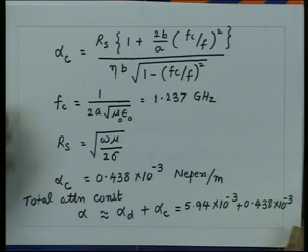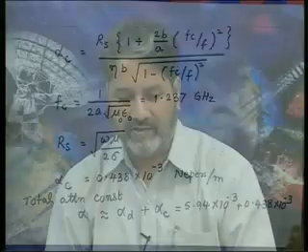So, these are some of the representative examples which you will see for the waveguide. Typically the waveguide dimensions are given, the frequency of operation is given, and we have to find out the modal characteristics of the waveguide, that is, how many modes will propagate. And also we have problems where a dominant mode is propagating on the waveguide, and then we would be interested in finding out how much power will flow, what will be the field expressions for that mode, what will be the Poynting vector, what will be the loss, and so on. So, once we see these problems, then on similar lines other problems related to the waveguide can also be solved very easily.